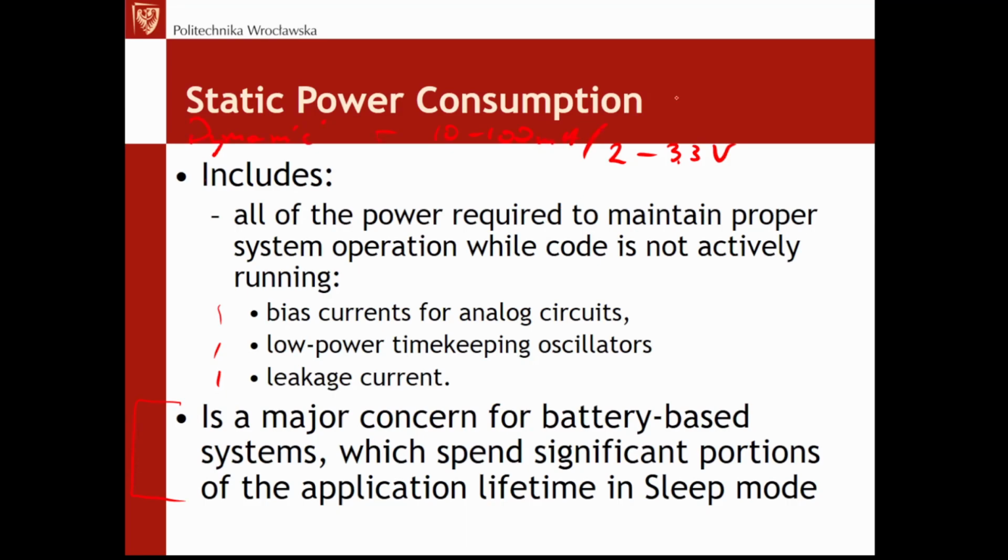In case of static power consumption, we usually talk about 1 to 100 microamps only, of course at the same voltage, because naturally the power supply is the same. So as you can see, the difference is 3 orders of magnitude between the static and dynamic factors in the expected power losses.